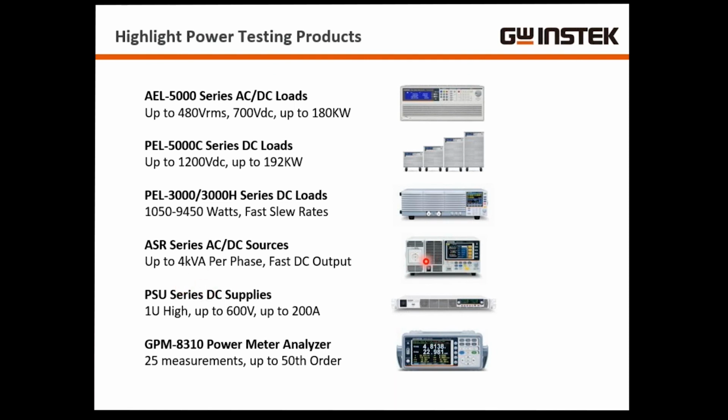Now, I do want to say that when you put these 3-phase systems into a wye configuration, you will have a full line-to-line voltage. For example, if you have 277 volts line to neutral, with a line-to-line wye configuration, you'll have 480 volts. So you have a higher capacity than you would ordinarily have with just a single-phase unit.